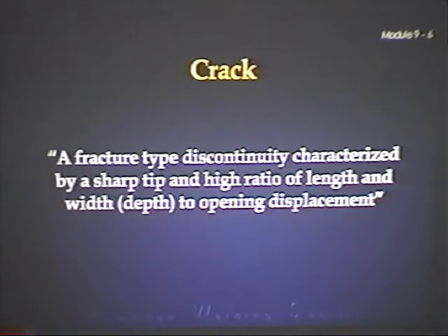If cracks resulting from the arc strike appear on the surface, a weld bead must be deposited over them. The bead should be made reasonably long and wide in order to increase the amount of heat input to the defective area, thereby reducing the cooling rate. Of course, the cardinal rule to follow is never to strike the arc outside the weld joint. That's the main thing. Just keep everything right in the joint.